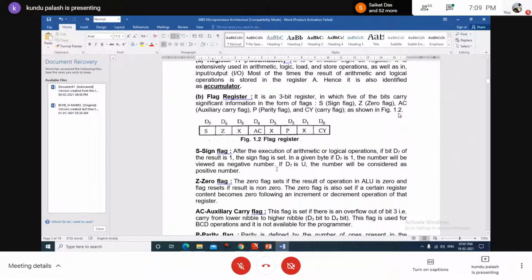For example, there are signed arithmetic as well as unsigned arithmetic in binary operations. So you require the knowledge of what is sign bit operation, signed number operation. For example, generally we are conversant with the unsigned operation. That means every binary number is treated as a positive integer. Accordingly, the summation will proceed. But if the binary number is expressed as a signed number notation, then generally the most significant bit carries the sign information. For example, if the most significant bit is 1, the number is negative, having magnitude as well as the sign bit. If the most significant bit is reset to 0, the number is treated as a positive number. For a sign bit system. Otherwise, for an unsigned number, there is as such no sign information in the most significant bit.